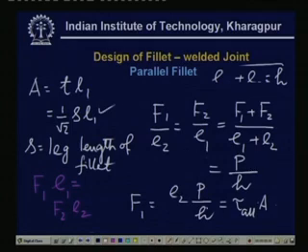So, this is how the design is to be made. I emphasize here, I stress again, that the designs must be such that the welded joints do not experience any bending stress. This is very important, because bending stress is very detrimental to the joint efficiency, or it leads to joint failure. So, this must be remembered very well.